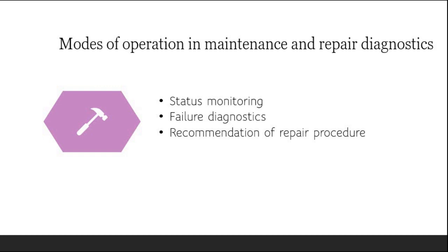In status monitoring mode, the diagnostic subsystem monitors and records the status of key sensors and parameters of the system during normal operation. It serves two important functions in machine diagnostics. First, providing information for diagnosing a current failure, and secondly, providing data to predict a future malfunction or failure.